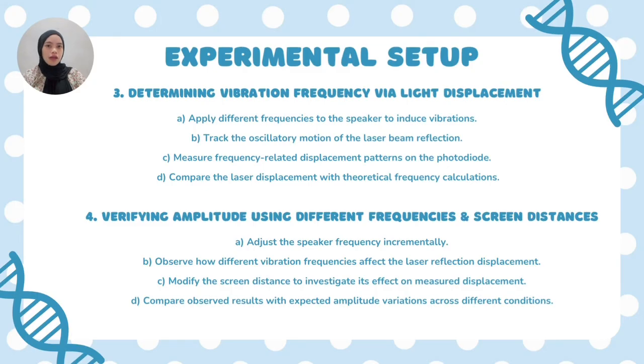Lastly, verifying amplitude using different frequencies and screen distances. Adjust the speaker frequency. Observe how different vibration frequencies affect the laser reflection displacement. Modify the screen distance to investigate its effect on measured displacement. And compare the observed results with the expected amplitude variation across different conditions.